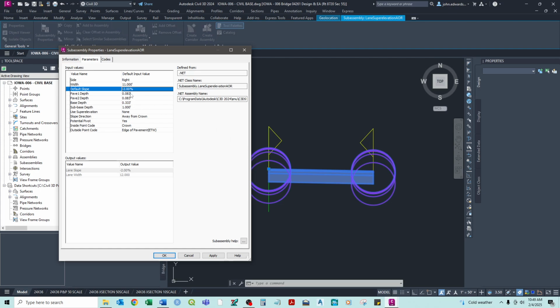Okay, but we're only going to be just laying 6 inches of gravel on this thing. So we're going to change all of these to 0 except for the top one, and we'll put that at 0.5 because it's feet.